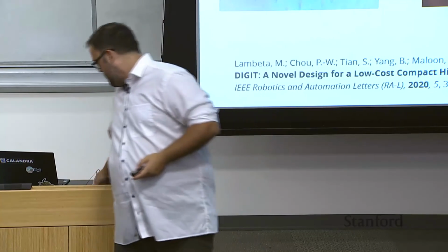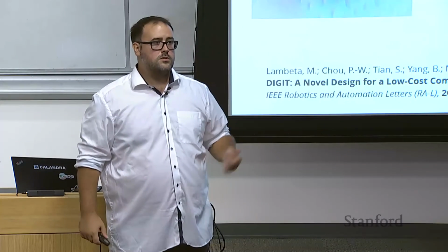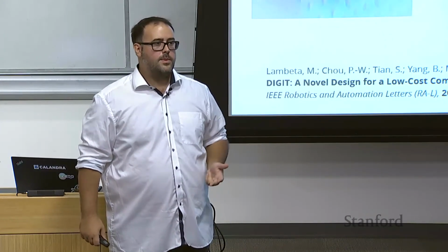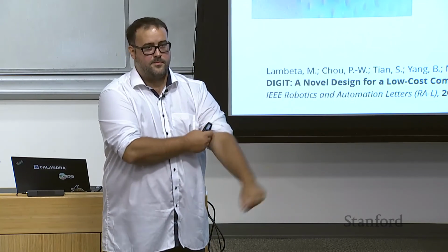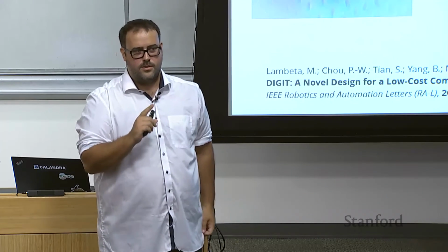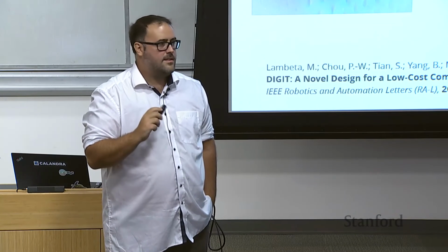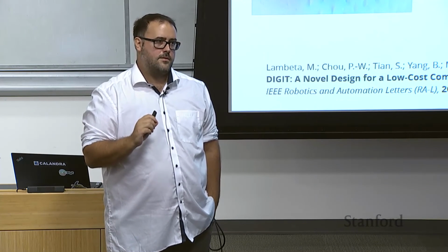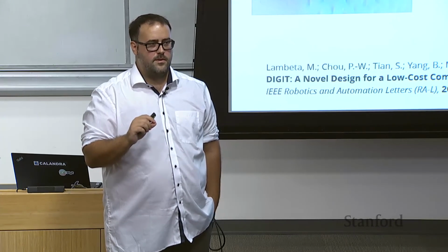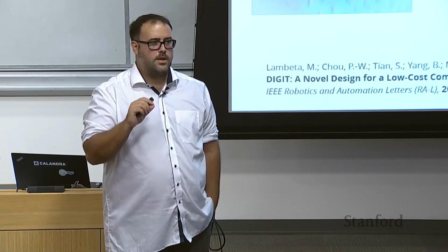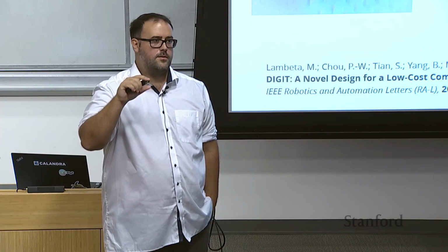So these are some of the, in my opinion, very big advantages of vision-based tactile sensors. Resolution, manufacturing, reliability, these are pretty big items. Maybe another one which is not so much highlighted is that also the sensitivity of vision-based tactile sensors can be much higher than a capacitive or resistive sensor, because effectively you can tune the bandwidth, the dynamic range of your silicon based on the application.